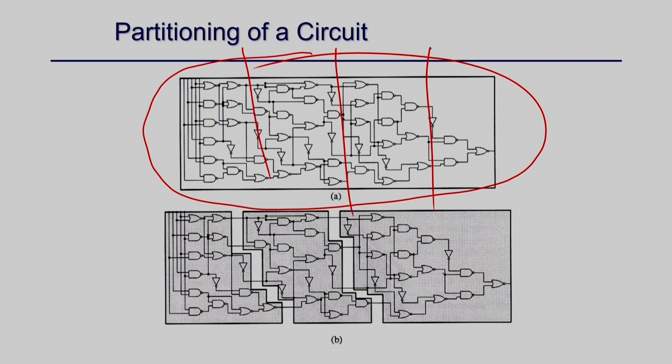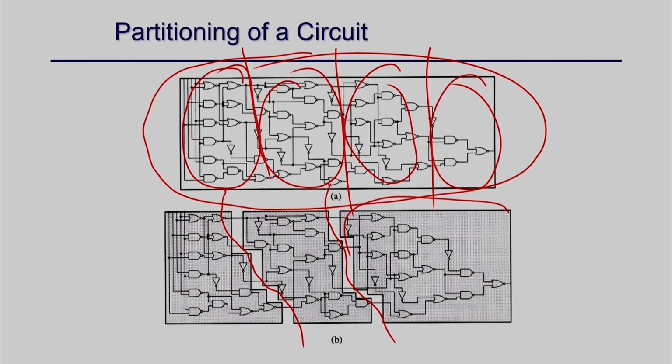You partition your design into small components, and you try to place this together, this together, and this together, something like this, right. Similarly, what is shown here is a partitioning. We have three partitions, and I try to place each partition independently, right. Once that is done, I can again recursively do the same partitioning within this component, or this component, until I have a module which is easy to handle, right. So this is what partitioning of the circuit means.